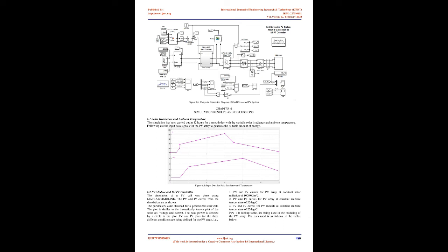The Rp model, or single diode 5-parameter model, adds a shunt resistance, Rp, to the 4-parameter model and therefore considers the leakage current to the ground. Figure 4.2 shows the equivalent circuit and the equation shows the current-voltage, IV, characteristics. This model is used for implementation in Simulink/MATLAB in this thesis. Figure 4.2, Rp model, single diode 5-parameter model.